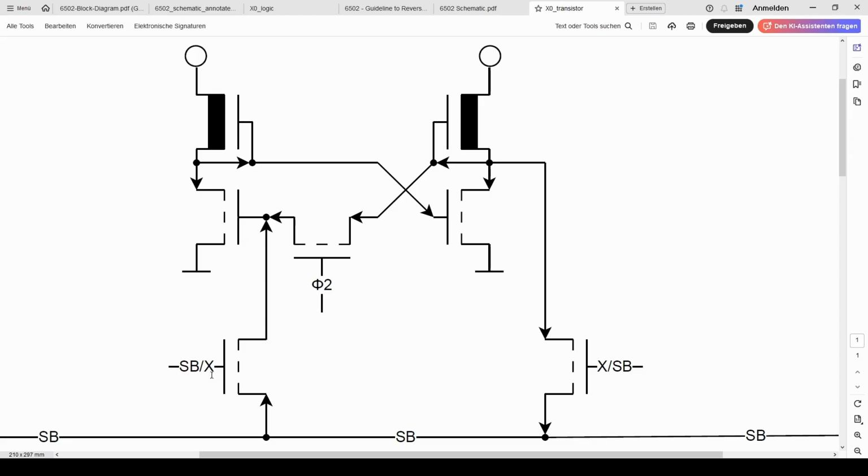So normally transistors conduct only when there's current on the gate. In this case, it conducts unless there is current on the gate. With that being said, for our purposes, we don't really care about this thing's behavior at all, because the drain is connected to the gate, and a depletion mode transistor with the gate and drain connected is called a diode connected transistor, and that just acts as a resistive load.